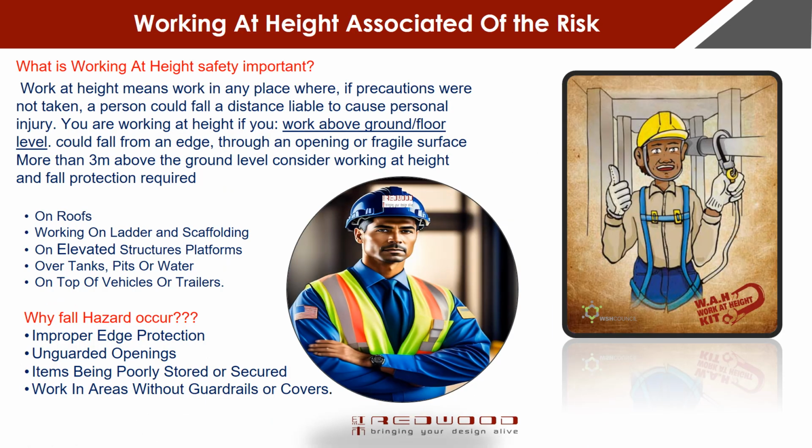Work at height refers to any work performed in a place where a person can fall from a height and be injured. Under Singapore's Workplace Safety and Health (WSH) requirements (MOM), this includes work on ladders, scaffolds, rooftops, platforms, edges, and openings. Summary: under the SG WSH standard, fall protection must be used, e.g., harness, lifeline, guardrails, when there is a risk of falling. Proper risk assessment and safe work procedures must be in place before starting work.